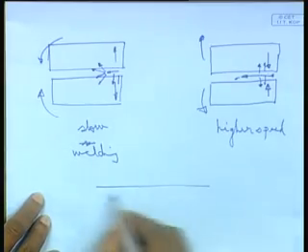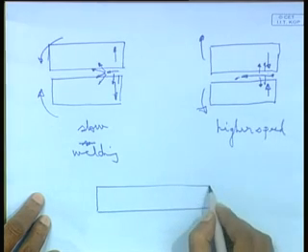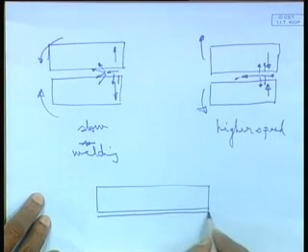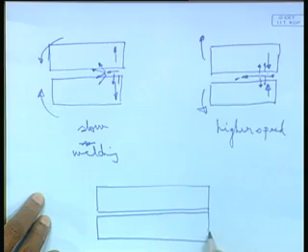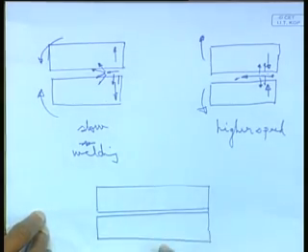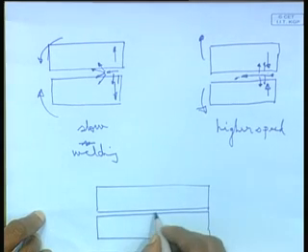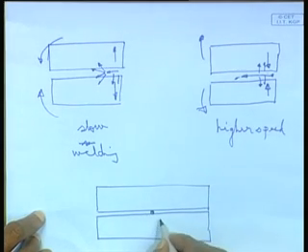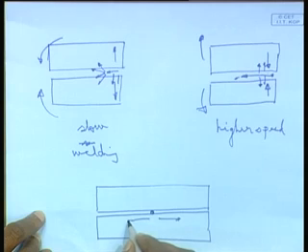That means, for a long welding run you cannot weld from one end. So, what is the solution? You have to start at the middle and go both ways, I mean outward. That means, for a long welding, whether it is a manual welding or automatic welding, it is immaterial, because in both the cases you are having difficulty. Either it is opening up or it is closing. The difficulty is the same. That means, you cannot weld from one end. So, the best is to start from the center and go simultaneously outwards.